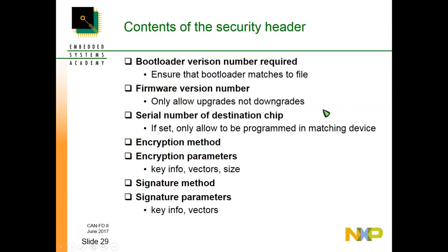What's in this security header? The information we have in the security header is the bootloader version number, to ensure that the bootloader version matches what we have in the file. If these don't match up, then programming might not work, so we need that version in here.